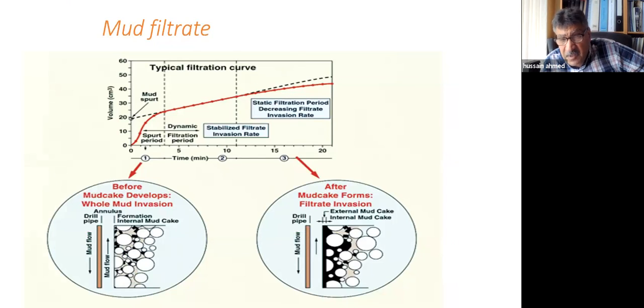So the skin factor could be coming from the drilling stage due to mud filtrate and debris from the drilling mud, essentially in overbalanced drilling. And these solid particles invade the area surrounding the wellbore, blocking the channels, and cause the black area here, which is very much an area of formation damage or invasion zone due to drilling.